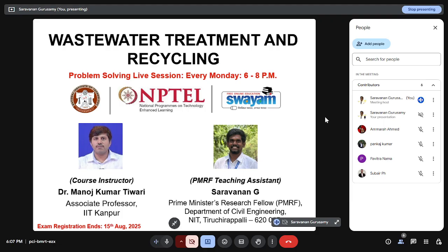If you have visited most of the sewage treatment plants, that is STPs, in your municipality or corporation, they follow a similar pattern of wastewater treatment systems. We are going to discuss the primary treatment system today, which comprises mostly of grit chamber, screens, and primary settling tank. These three are today's content agenda.